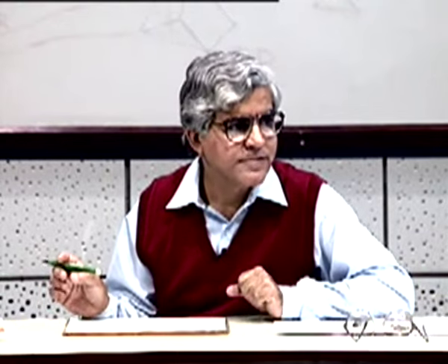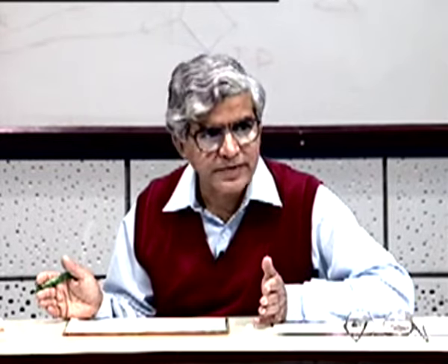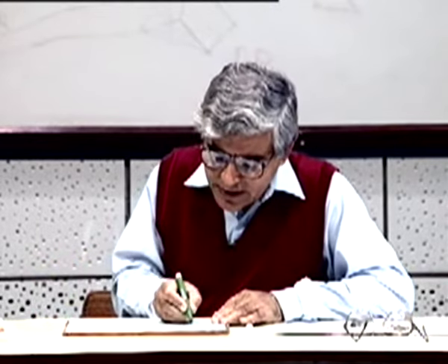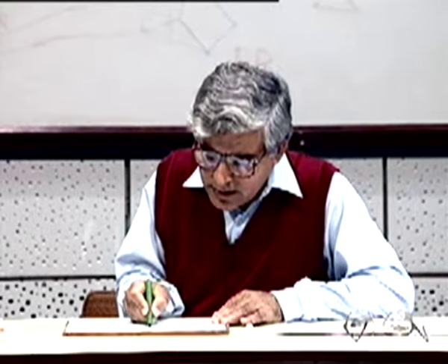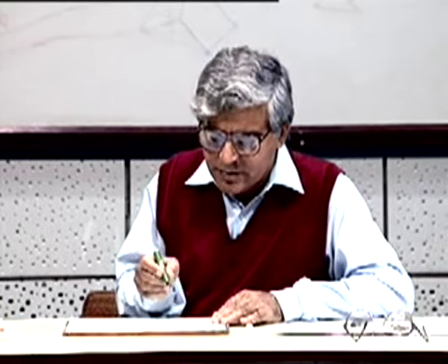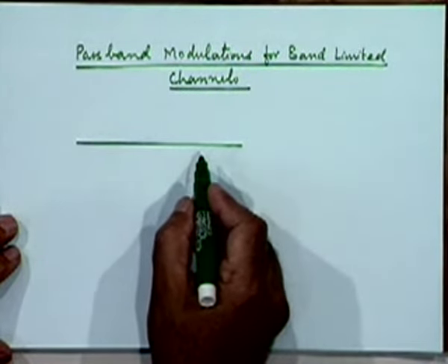If you may recollect, the essential feature is that more or less we are constrained to use either a single pulse shape whose bandwidth lies within the channel bandwidth, right, or at best we can have multiple pulse shapes all satisfying the bandwidth constraint. But if you may recollect, we suggested for baseband band limited channel digital modulations essentially some kind of a QAM kind of modulations, right.